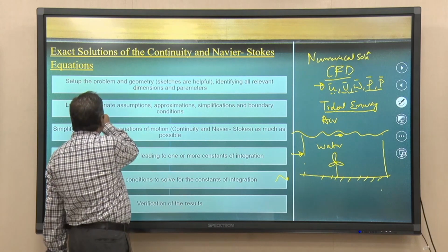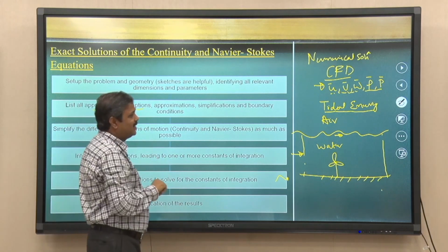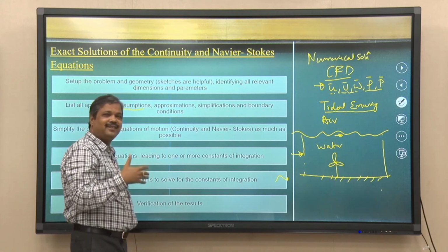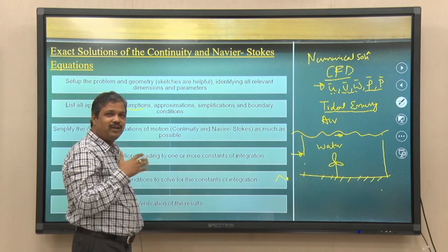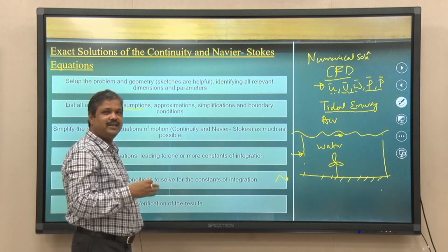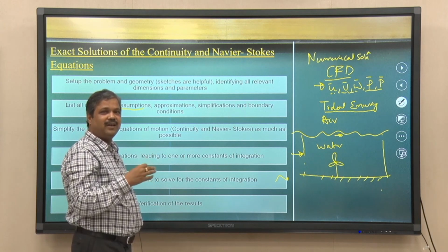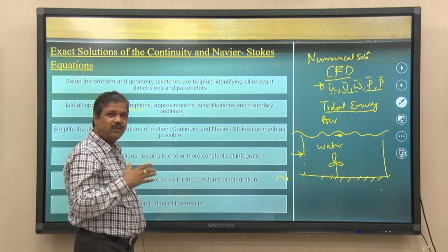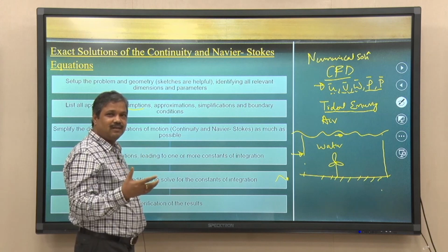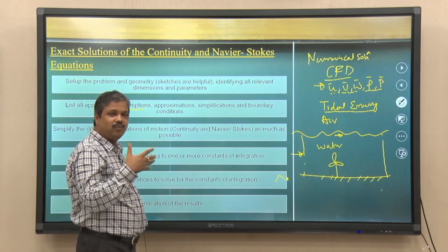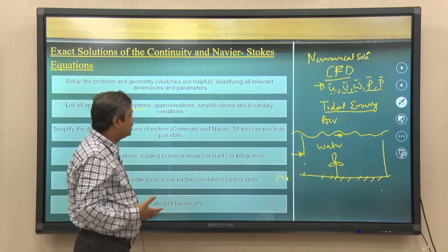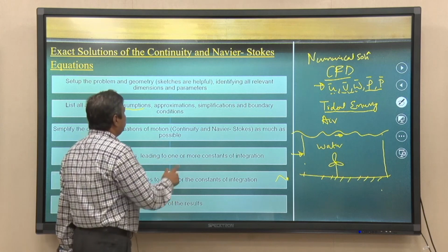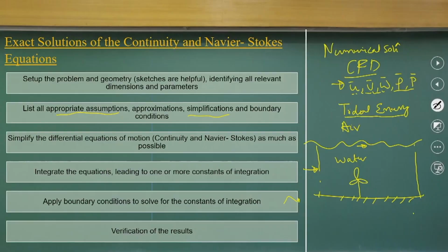Always you have to look at the appropriate assumptions. As I said, I am repeatedly telling you, the Navier-Stokes equations that we have derived are only for incompressible, Newtonian and laminar flow. So, we have not considered turbulent flow, temperature variabilities or density variabilities; we just consider Newtonian fluids. Even so, we should know what simplifications we are making and what boundary conditions we are imposing here.